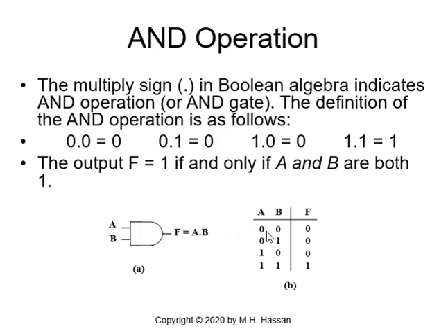While the truth table is A, B, and the function F. When we fill the truth table, we fill the least significant bit, which is B, 0 1 0 1, then A, 0 0 1 1. If we have three variables, we fill 0 0 0 0 1 1 1 1 for the third variable, then 0 0 1 1 0 0 1 1, then alternating 0 1 0 1 0 1 0 1. The third variable will be 4 zeros and 4 ones.